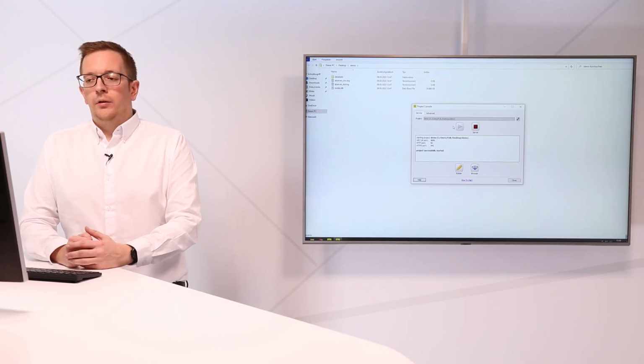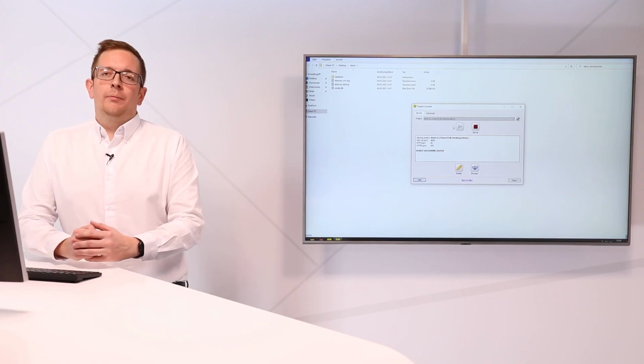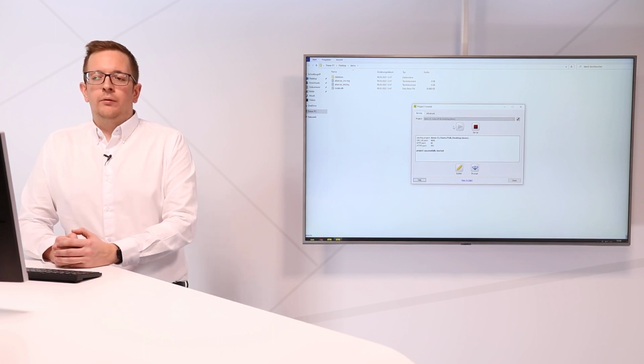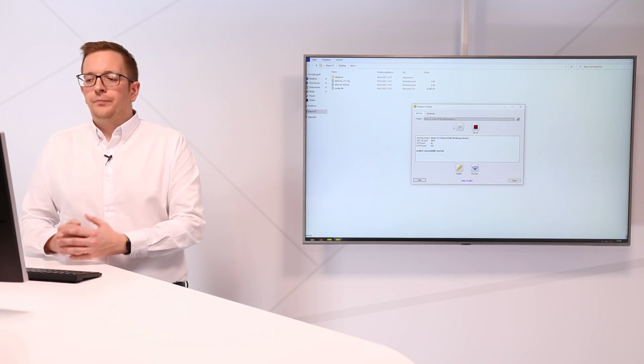The rules are simple. If you start the atvise server, it is looking for a file called nodes.db in the project directory. If it's available, this project will be started. Otherwise, a new project file will be created for you.